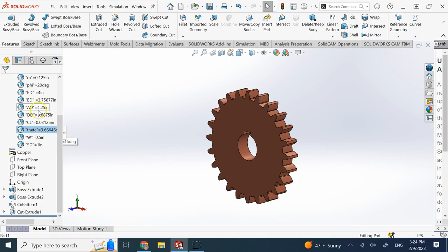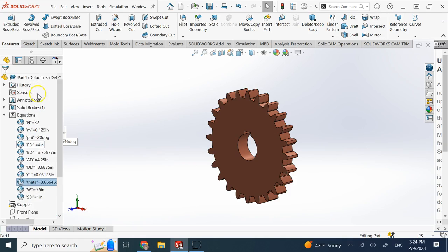In the involute curve also, it did not necessarily do a beautiful job, because it did not take the radius of the base for me in that equation driven curve. So there are a few places where the window did not allow you to insert parameters, although we put them in double quotation marks. I'm looking for solutions, and if I find one, I'll let you know in my future videos.